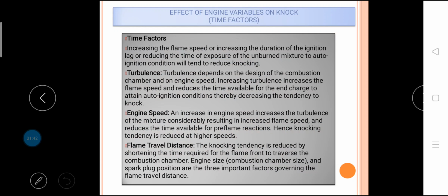This figure shows the variation of knock limited compression ratio with respect to equivalence ratio for isooctane. The maximum tendency to knock takes place for the fuel air ratio, which gives minimum reaction time. Thus, the most predominant factor is the reaction time of the mixture in this case. In general, except at rich end, the behavior in the engine follows the same pattern as the fuel air ratio versus reaction time. The drop in IMEP at very rich end is caused by large drop in thermal efficiency.